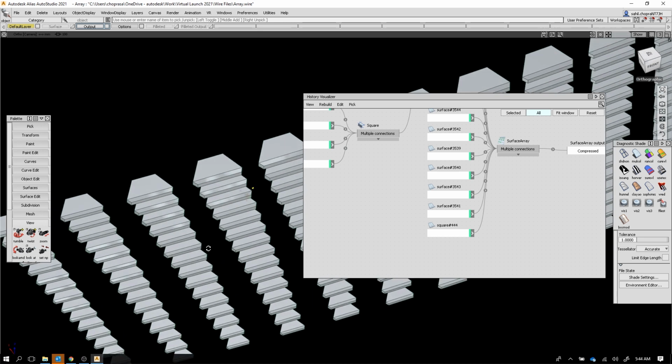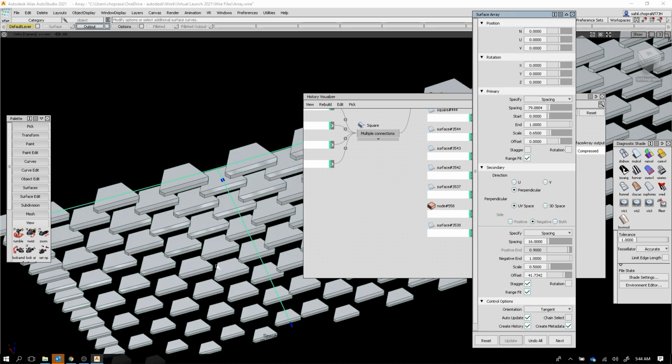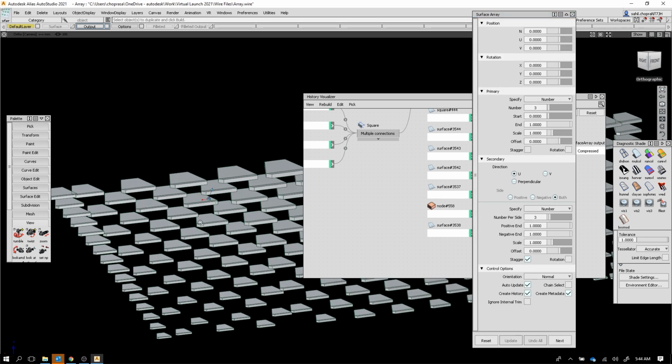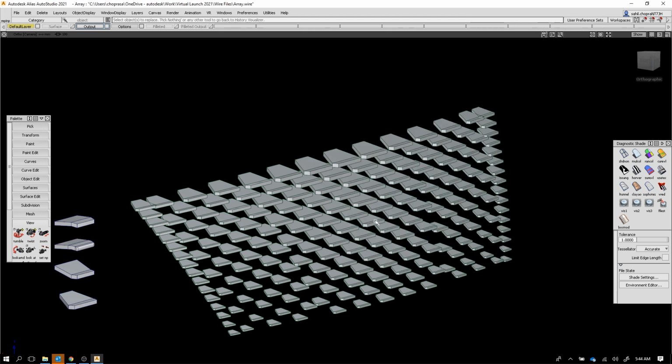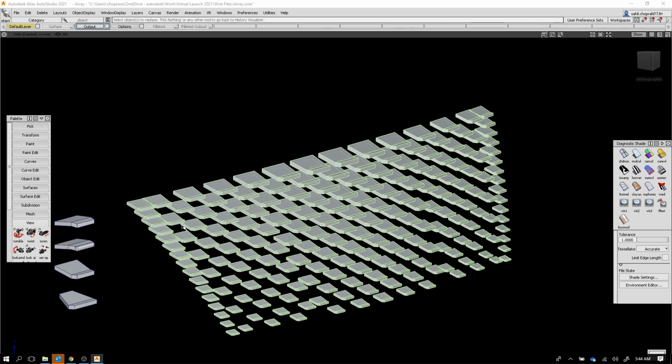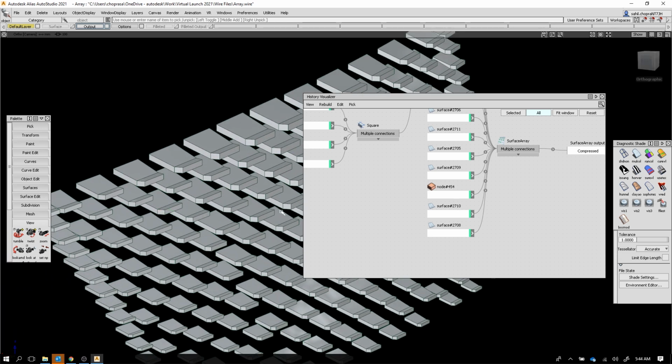Of course, this doesn't need to just be used on engineering data. This could be any sort of data that I'm building: bi-rail, square, fillets. Any tool that has history in Alias works this way, the array tool, for instance. I can now replace my input entities. For example, a circle, change it to a hexagon, and my array geometry will rebuild automatically if I've drafted and filleted around that. All that geometry will rebuild also. So very simply, replace the input, and then everything rebuilds automatically.